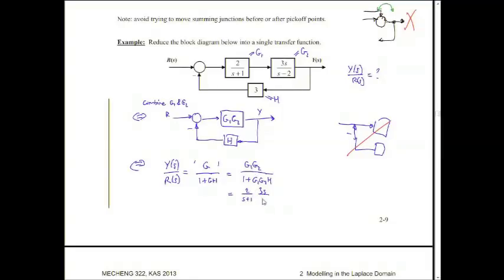The actual transfer functions: 3s over s minus 2 over 1 plus 3 times this thing, so it's 3 times 2 times 3s, which is 18s over s plus 1, s plus 2. Because G1 G2 is on the top and it appears here in the bottom. So I multiply this out, 6s over s plus 1, s minus 2, and I'm multiplying it by 3, which is H.